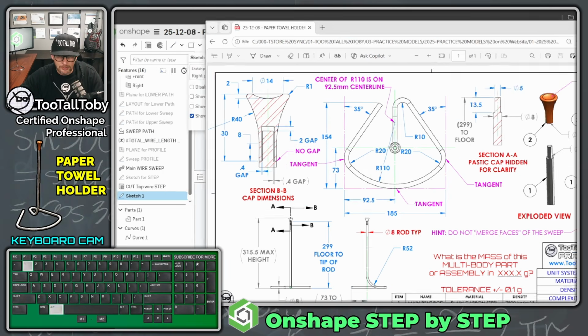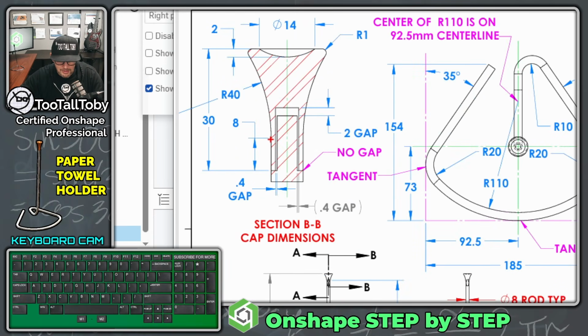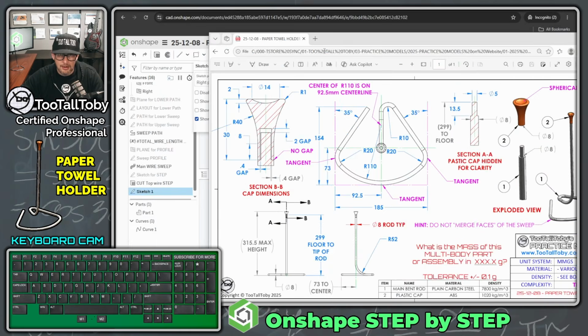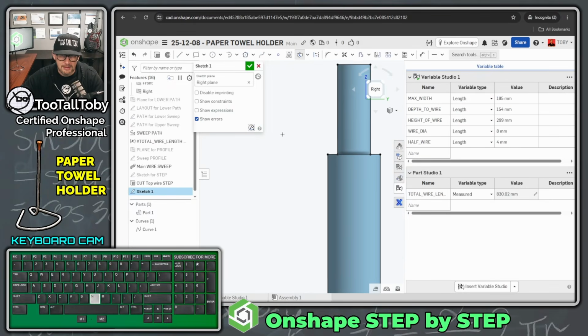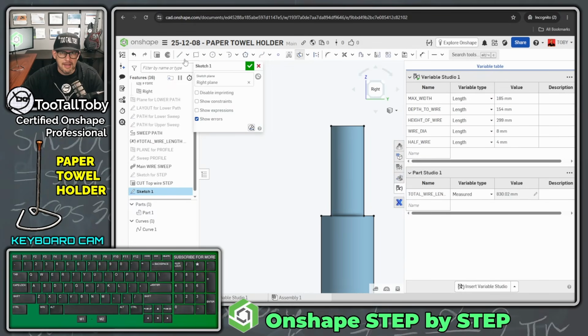So for example, to create this 8 millimeter section that goes up here, 8 millimeters straight, and then create this 40 millimeter section, 40 millimeter radius, and then this 1 millimeter section, and then this flat spot here. Well, what I could do is get to a normal view, press N, rotate this thing normal. Now I can get into the line command and I can just single click here and move up. And this is going to come up to 8 millimeters. Then I can move my mouse away, come back, touch the end point. Now I can come off of here with a radius of 40.